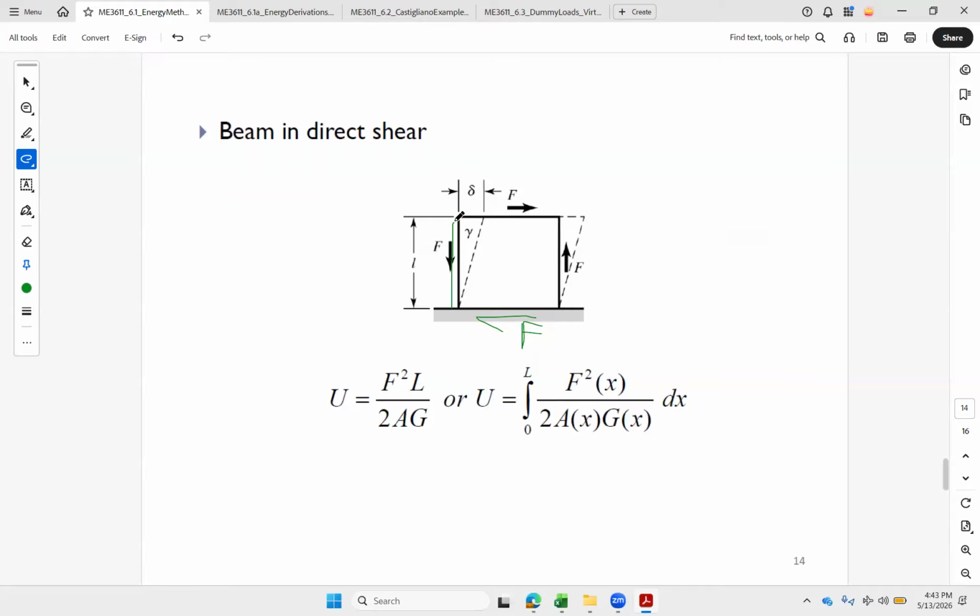We've got some bars right here, and the way we can overcome this torque that's generated by the right and left hand movement there, that tends to want to put it clockwise, we put a counterclockwise couple right here. So there's a bar right here. This vertical column, we'll say, is getting pushed up. This one is pulling down. All right. So this one is actually in tension, this one in compression. We're going to assume that these act, rather than as beams, as bars.